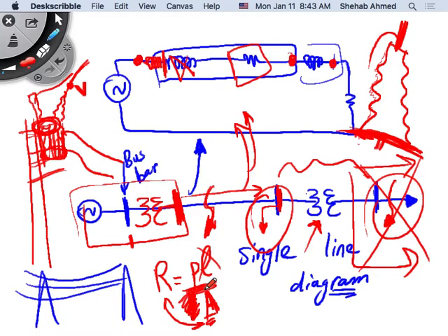These transmission cables would also be bare if they're hanging on top of transmission towers. Are you worried about somebody holding onto it? You're not, so you're not going to add an insulator jacket around it. You're not going to add big, heavy insulation on the whole transmission cable, for example, from the power plant all the way to the industrial facility in Ras Laffan. You're transmitting power there. Why put an insulator? It's bare copper, a bare conductor, copper or aluminum. We'll talk more about that.